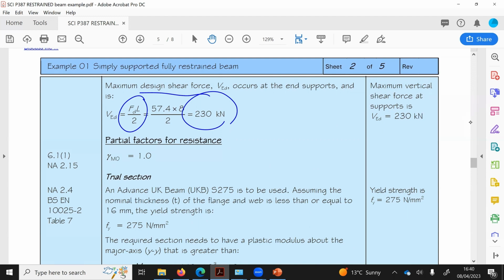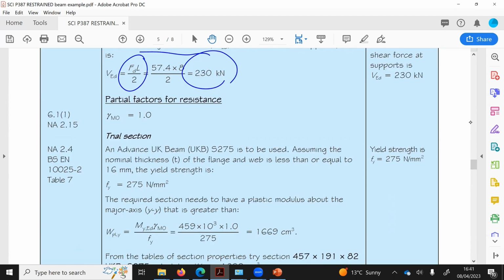But if a beam is carrying heavy concentrated point loads, if it is a plate girder, if it is used in bridges, then you have to take into account shear. But here I will follow the process. I will carry out all 3 design checks: moment, shear, and deflection or serviceability. Firstly, we have to come up with a trial section.